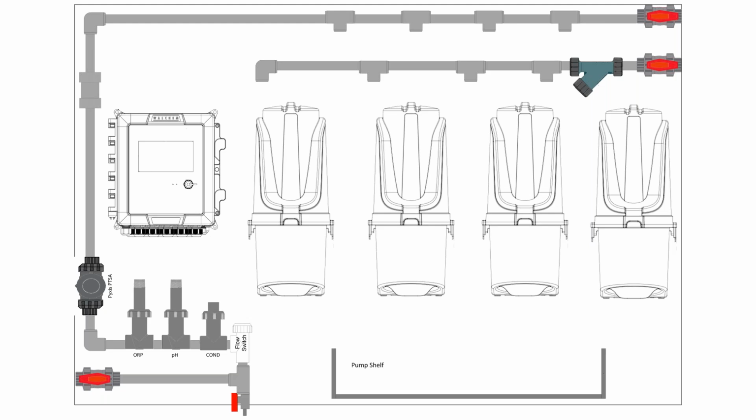One point I did want to make, Tom, that you had touched on, we do recommend only makeup water for that system for the dissolvers. So whatever quality water you're using as makeup, whether it's boiler makeup or cooling tower makeup, we want that to be the same best quality pre-treated water.